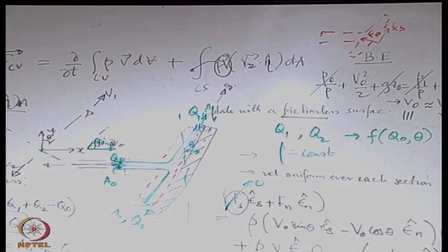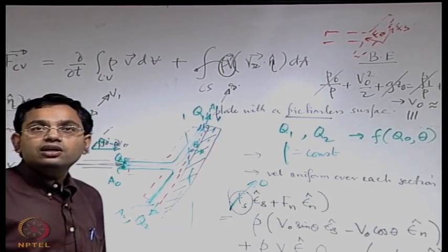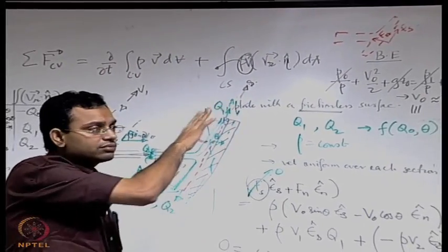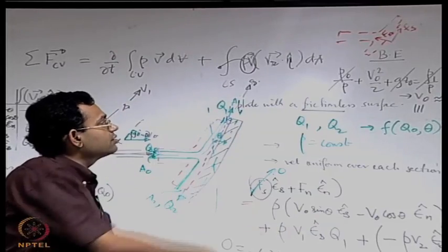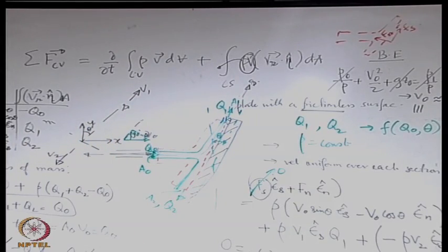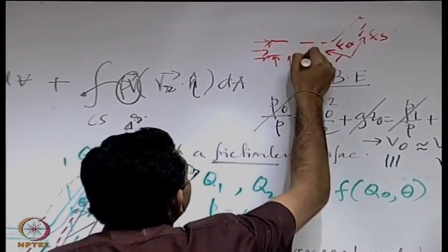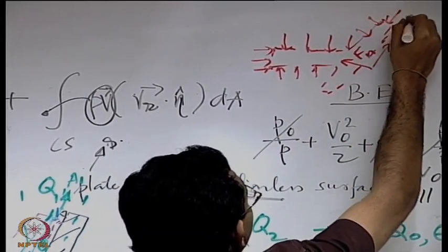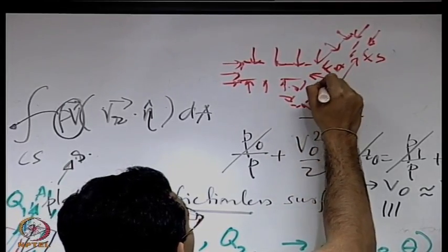Yes, think of the fundamental considerations of forces in continuum mechanics that we discussed. You have surface force and body force. So for body force, we have considered the weight, just not shown in this plane because it is not significantly there in this plane. For surface force, pressure distribution is there, so there is a surface force from all sides, normal to the areas.